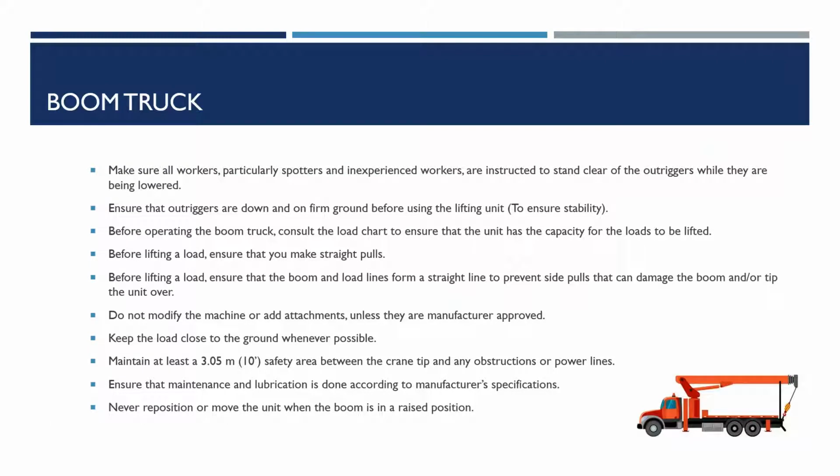Boom truck. Make sure all workers, particularly spotters and inexperienced workers, are instructed to stand clear of the outriggers while they are being lowered. Ensure that outriggers are down and on firm ground before using the lifting unit. Before operating the boom truck, consult the load chart to ensure the unit has the capacity for loads to be lifted. Before lifting a load, ensure that you make straight pulls.